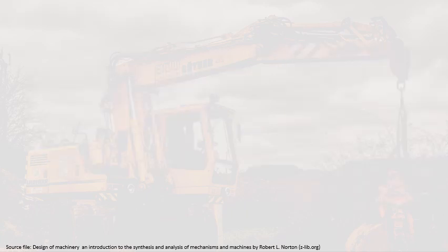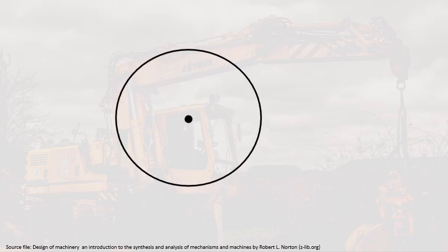So to illustrate how to draw the involute, say for example you have here a base circle and you would like to draw the involute between points A and E. So the involute tooth form can be drawn first by dividing the arc from A to E into equal arcs. So here I divided it into 4 arcs. We have AB, we have A to C, A to D, and A to E.